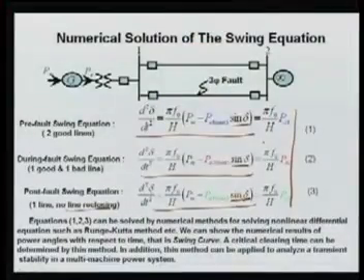But the only limitation is that we have made several assumptions. Those may not be valid for a big power system, and it is also not possible to reduce the system into a single machine infinite bus equivalent. Then we have to go for the complete, real-time practical system for simulation, and for that we have to solve these differential equations for all the machines, not only one machine. This is the case of one machine, so we have to go beyond this infinite bus system.